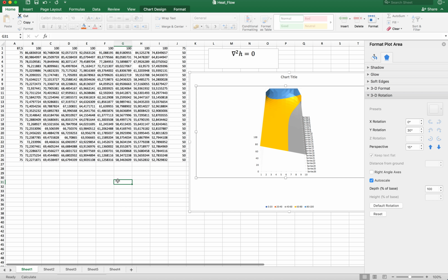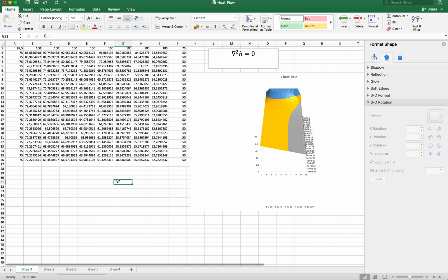Okay, so let's just select our data, just extend it here. All right, so now we've got a nice looking plot. But let's say I come along and I put my piezometer somewhere on the side. So now what we're viewing here is we've measured the piezometric head around the boundary of our site, and we're assuming that there's a no flux in the Y direction.